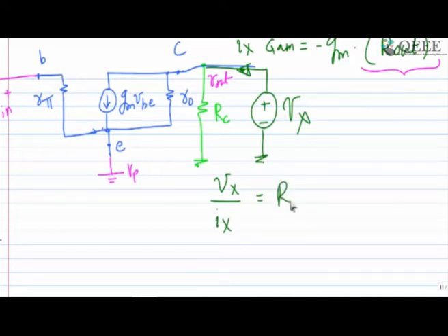And when I am doing this, my input source, or all the independent sources, should be shorted, or grounded. Wherever they are connected, all the other independent sources have to be grounded. This is the main tagline when you are doing the resistance analysis.